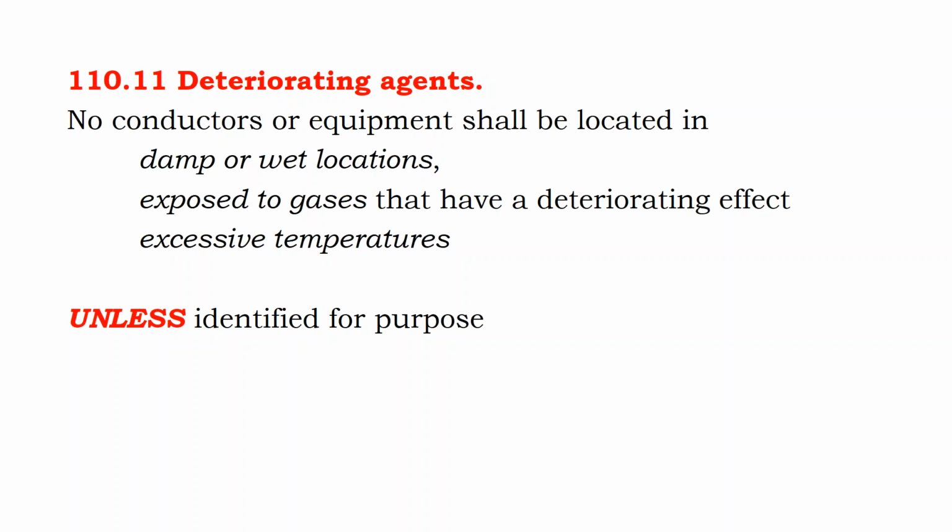But should you collect your gas? The thing is, flooded lead-acid batteries and any other kind of battery that requires watering maintenance will emit a corrosive gas that has a deteriorating effect on metal. Inside your battery room, you may have an electrician who is used to working in metal flex conduit. They have a lot of battery cables that are thick and only about 5 feet long going between your equipment to your battery bank, and they just put it in some metal flex conduit because it's easier than doing an EMT conduit run. Well, any kind of conduit, EMT conduit, metal flex conduit, if it's exposed to a corrosive gas, it can corrode.